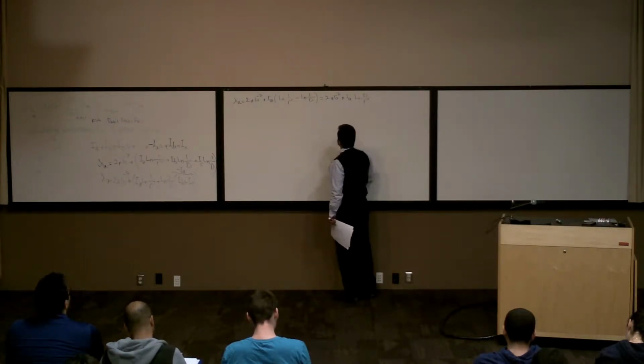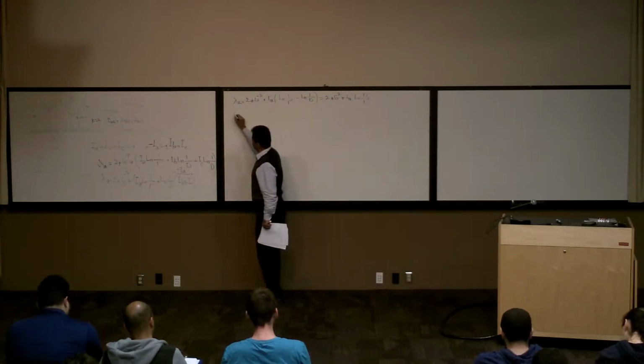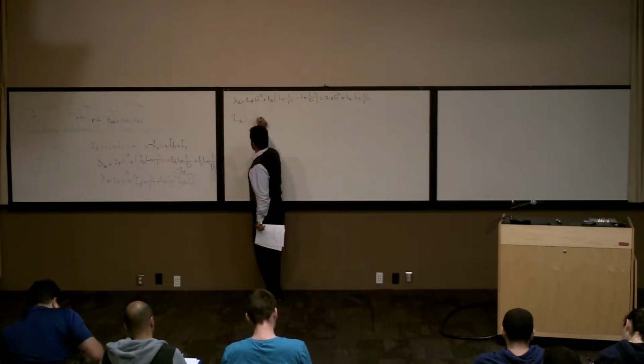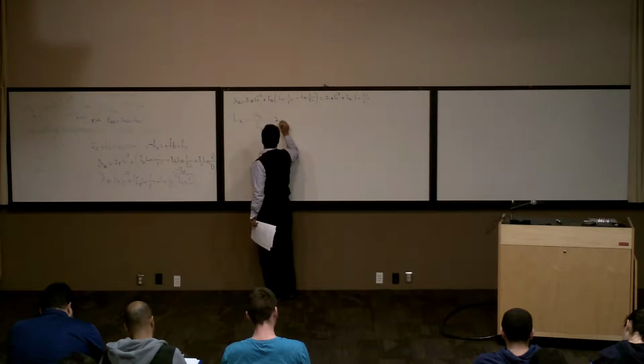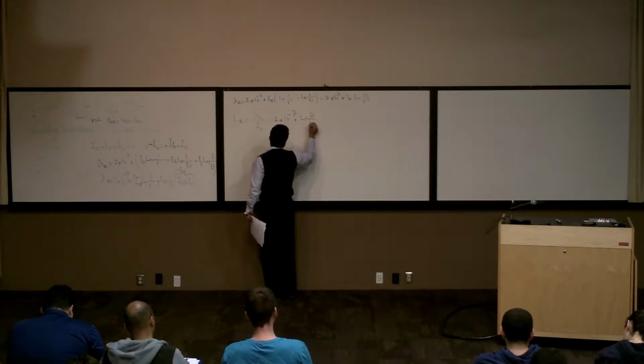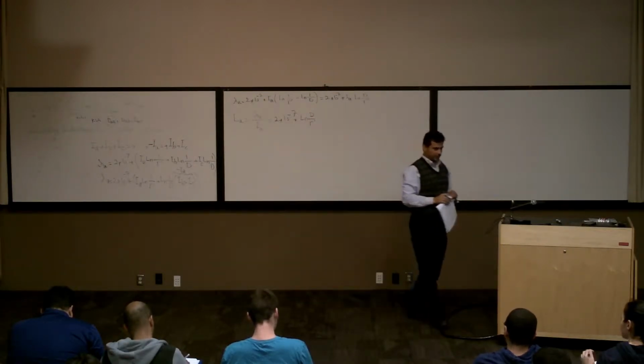How much is the LA, phase A? Lambda A over IA. So basically it's going to be 2 times 10 to the power of minus 7 ln of d over R prime. This is the inductance of phase A for the 3 phases.